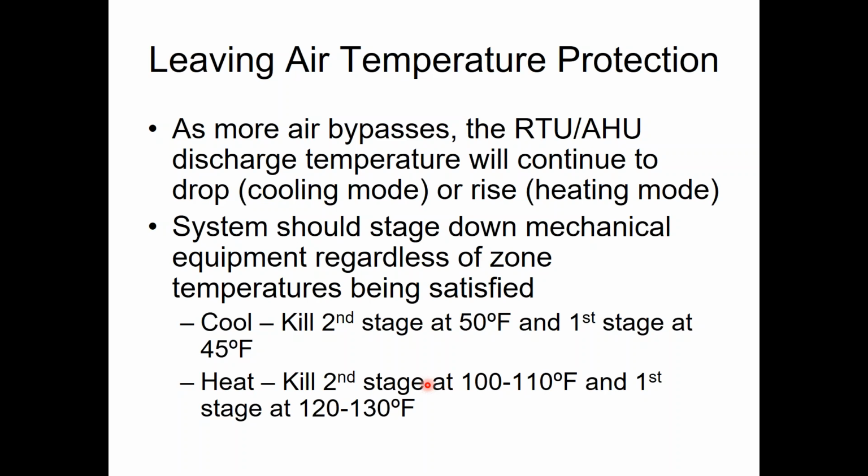So what I do is I put a discharge air sensor in the duct system so my VVT can be an early shut off, right? So he can sense that temperature, and let's say I set it for, in this example, 130 degrees. Maybe my rooftop has a limit of 150 switch in it. I set it for 130 in my duct system on the VVT, and if I get to 130, I'm going to back the stage off.